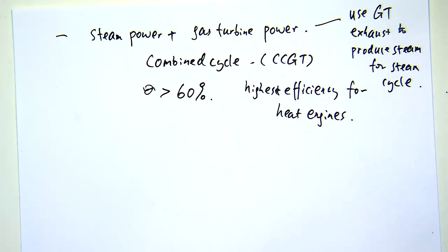The steam leaving the heat exchanger is at 6 megapascal and 325 degrees C, the condition at the inlet of the steam turbine and the highest temperature of the steam cycle. The gas turbine exhaust leaves at the saturated temperature of the produced steam, so that temperature needs to be found out as well.